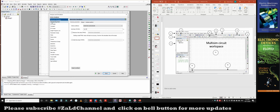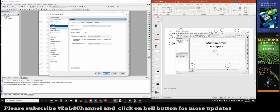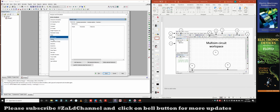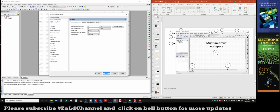We have all of the analysis in terms of AC analysis, which is small signal based simulation, transient, which is large signal simulation, and DC sweep. So for a DC circuit, for example, we can do the DC sweep to find the DC operating point of the circuit. And then some other advanced simulation like Fourier, Monte Carlo, and noise.